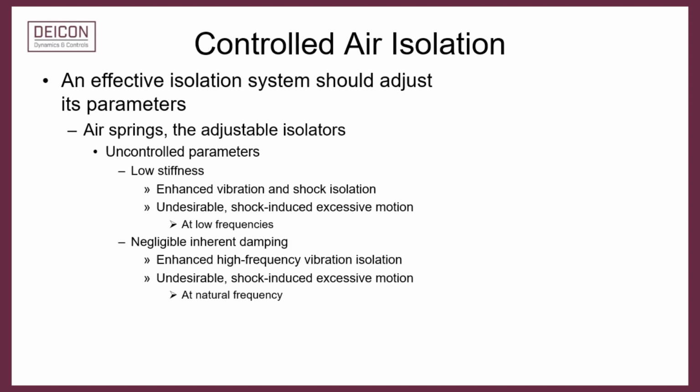In their uncontrolled state, air springs are soft with excellent vibration and shock isolation attributes. But this low stiffness could allow for occasional shock-induced excessive motion of the isolated equipment, which is undesirable. Air springs are also highly underdamped and thus provide excellent high-frequency vibration isolation. However, this very low damping results in poor shock isolation.